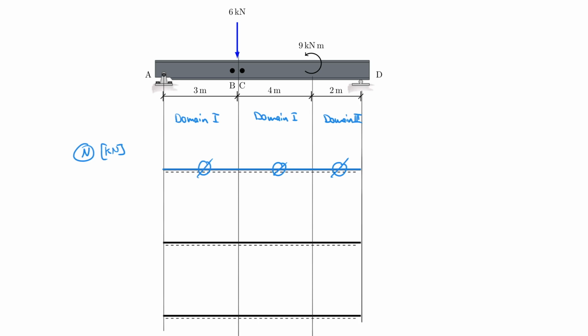And for my shear force diagram, the first value that I calculated at B was equal to positive 5, if I remember this correct. So let's say this here was equal to positive 5. And then at C, I had a value of minus 1, if I'm not mistaken. So that looks like this. And for the other location where I also calculated, remember I also calculated it here, right? So somewhere at this location to the right of that line. And I found that that was also minus 1.